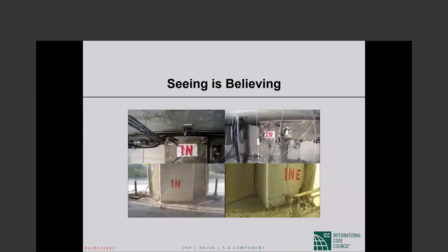So we include 1/4 of the designed live loads. That is the kind of logic. So if that's what you are asking, yes, seismic weight typically includes 1/4 of the designed live loads for storage facilities. BNBC, I think, is a little more complicated.